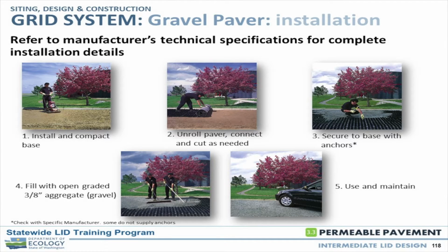Same processes, like in your excavation, backing out of the system, not driving on the finished subgrade, back dumping your aggregate so you're not driving directly on the surface of the subgrade. All those same considerations. In this case, you're looking at an installation sequence using a small compaction machine. Same considerations. Geotechs use the term firm and unyielding, and that's something you can describe, compacting that base.